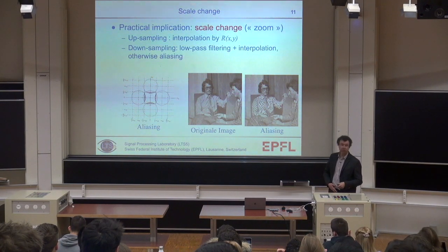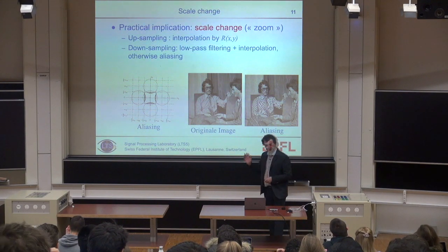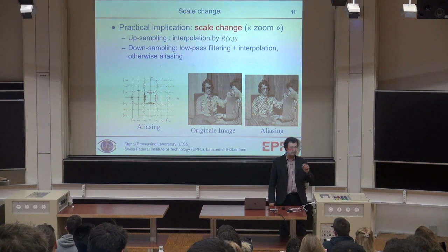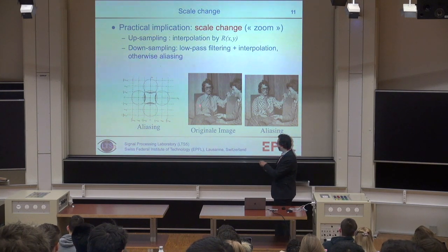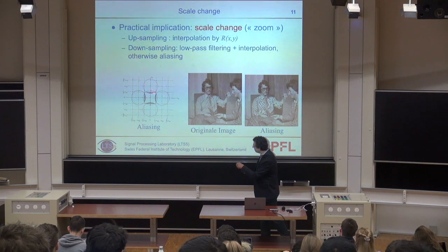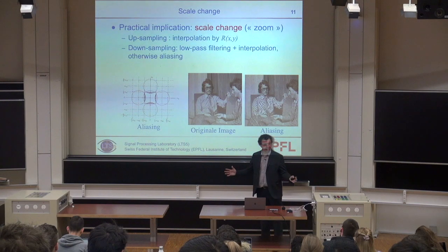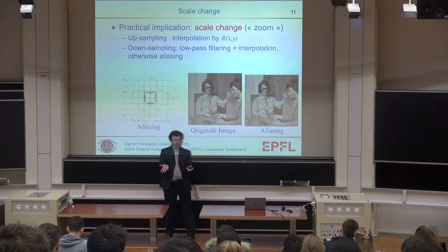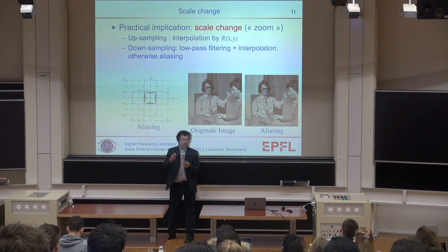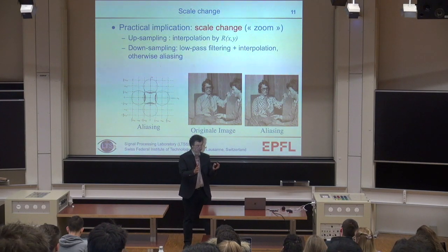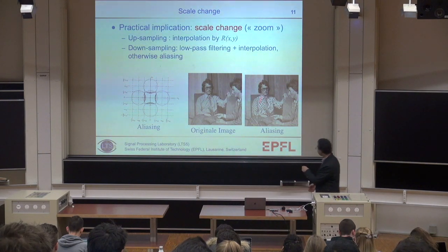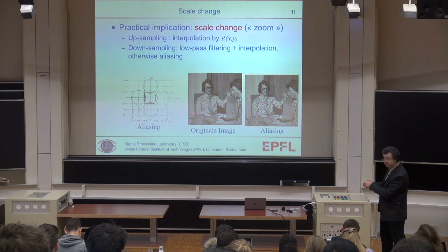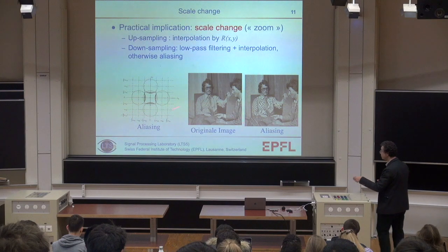This is what we see here. This is a very naive way to do it, but if I take this very old image, I like it because it's very oldish, and you just subsample it by taking 1 point every second point. So I divide my sampling frequency by 2 without doing anything else. You have high frequencies here that are really like high frequencies in my spectrum, on this circle, if you wish. And I subsample my image, so those replicas come down to the middle. And there are high values of the spectrum on the periphery of my replicas, so they really create high values of frequencies closer to the low frequencies, right? They interfere. And indeed, you see that in that image, which is downsampled, so bad quality, but you see the appearance of other frequencies. Here you see stripes at another frequency that didn't exist at all. It's just inventing frequencies because of the aliasing.